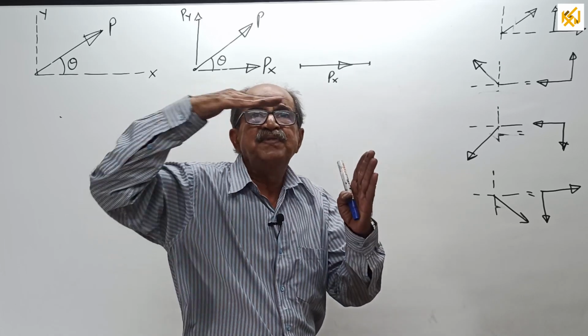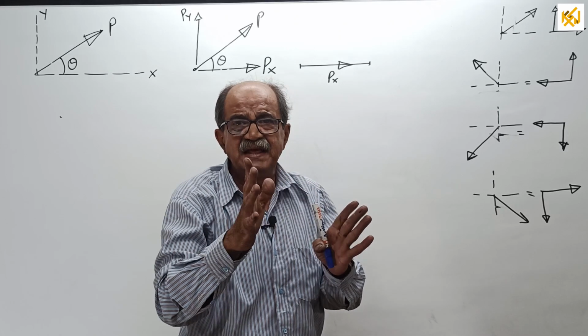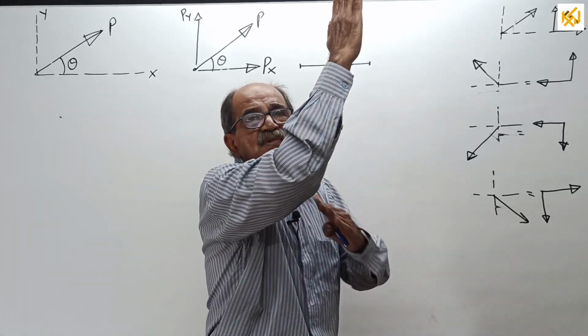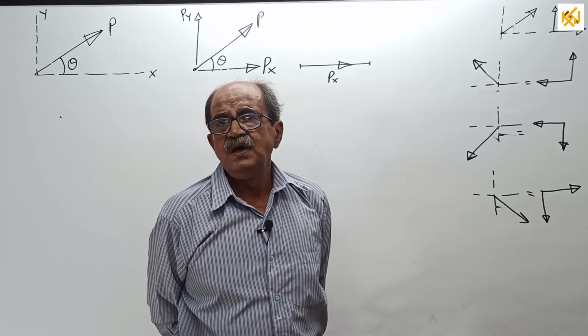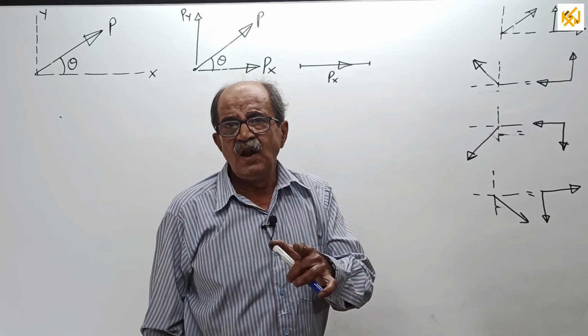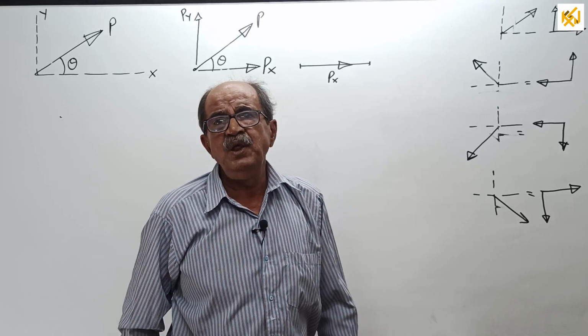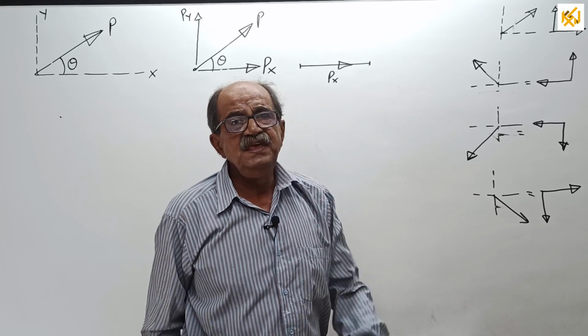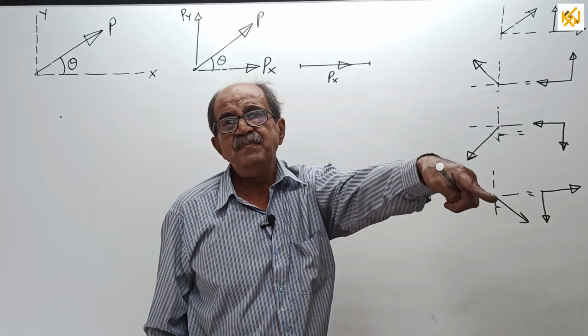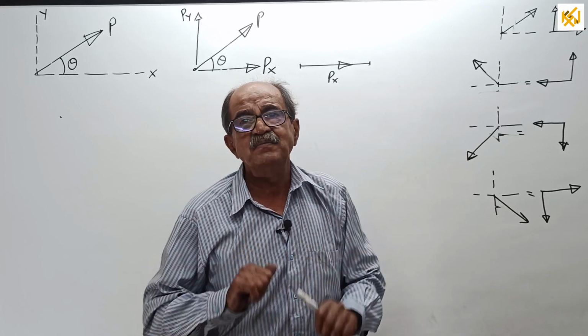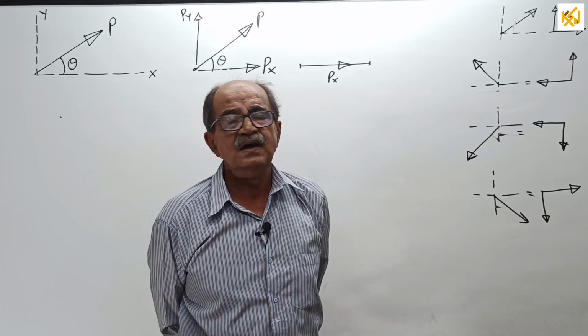And for a parabola of this type, I will explain once again later, I am just explaining only. This type with the base, the CG will be at 1/4 and 3/4 from the ends along the base, depending on from where you are locating the CG. All these I will prove because it comes in SFD BMD. We should first draw the diagram, then only we go for area.